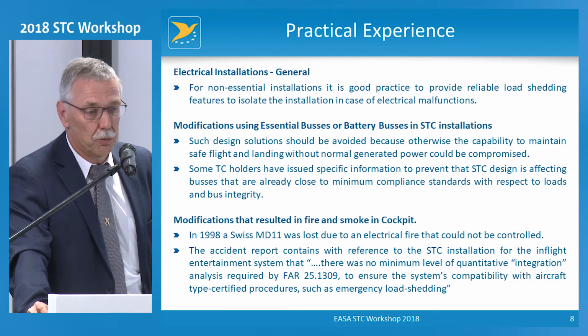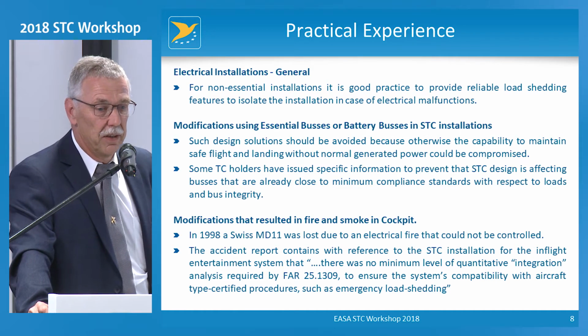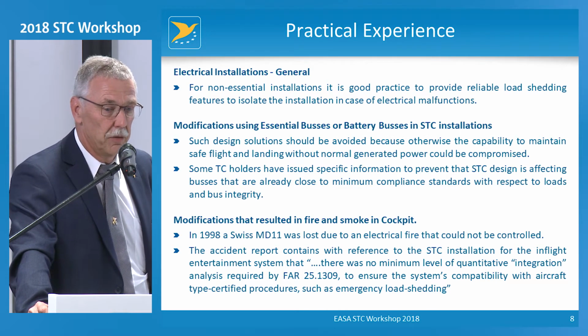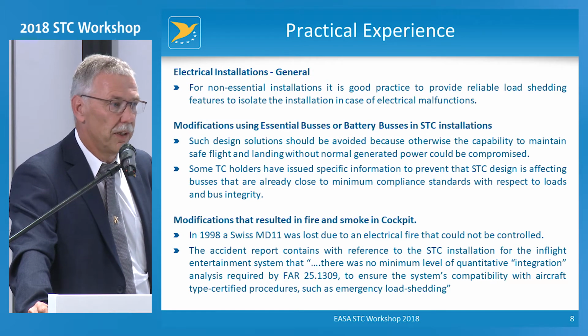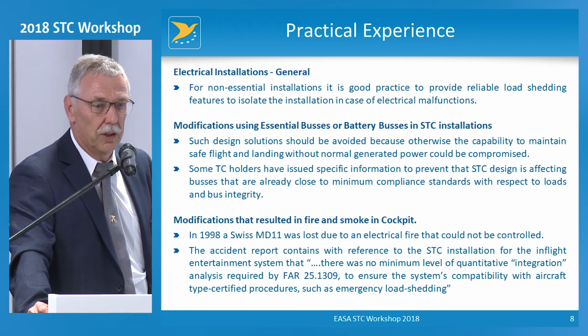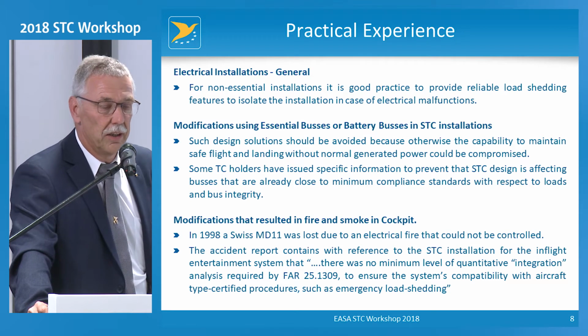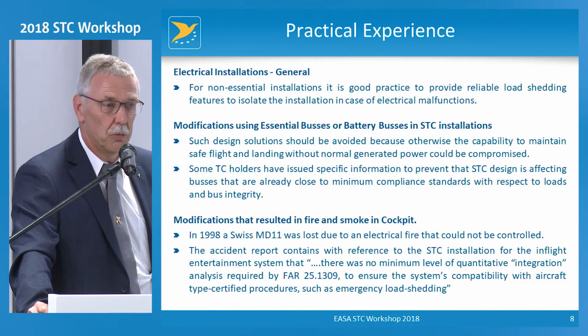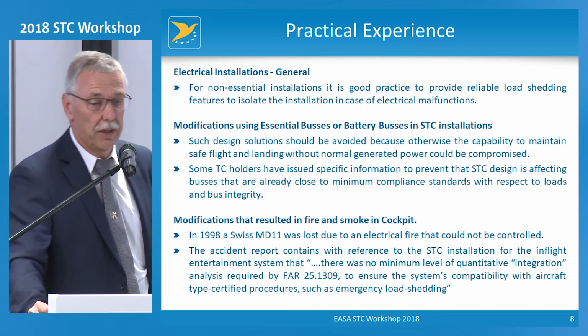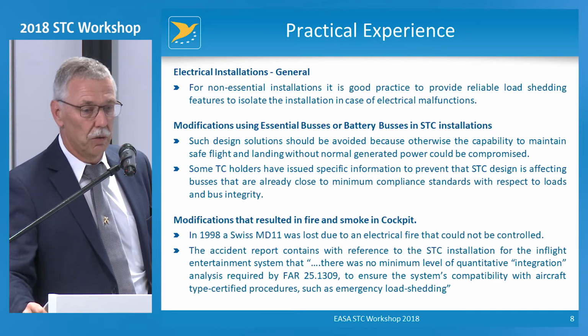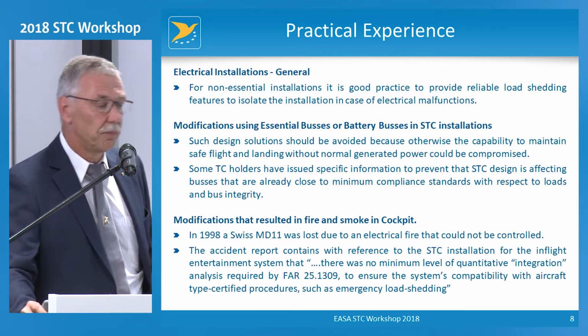The first line is probably kind of guidance, that it is good practice, if you have a non-essential system that you install via an STC, to do load shedding so that the loads are shed and the system doesn't function anymore in case of electrical problems of the basic aircraft. That's something that people do, some others don't, but I think it's a good practice.